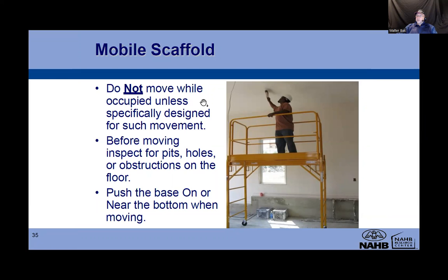All right, mobile scaffolds. When it comes to safety of mobile scaffolds, do not move them while occupied unless specifically designed for it. If it's designed to be moved, yes, but otherwise you should get off of them, move them, and then climb back on again. Before moving, inspect for pits, holes, or obstructions on the floor. As I always say,